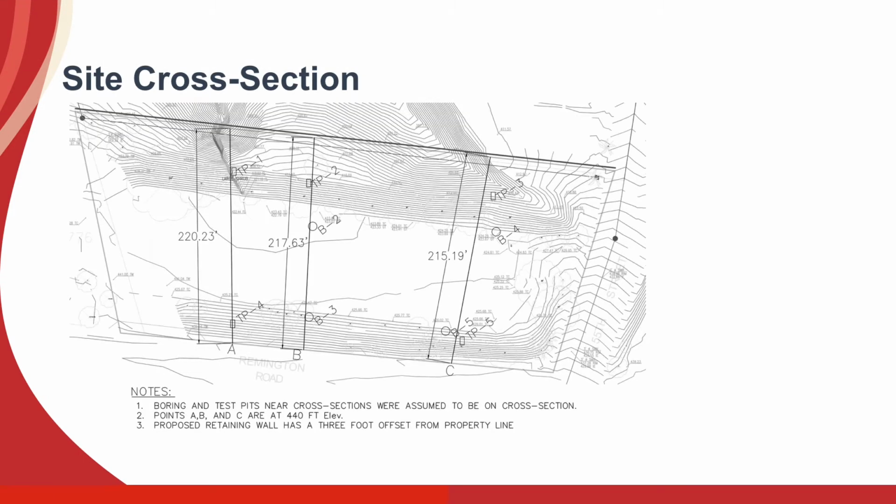The first part of the geotechnical analysis was the review of provided boring and test pit samples from Group Delta to determine the soil conditions. A series of cross-sections were made from the site layout with the location of the boring and test pit samples. Using these cross-sections, profiles were created showing soil conditions under the proposed foundation location. ASTM Standard D2487 charts and nomenclatures were used to classify the soil and understand the strength and potential for loading.